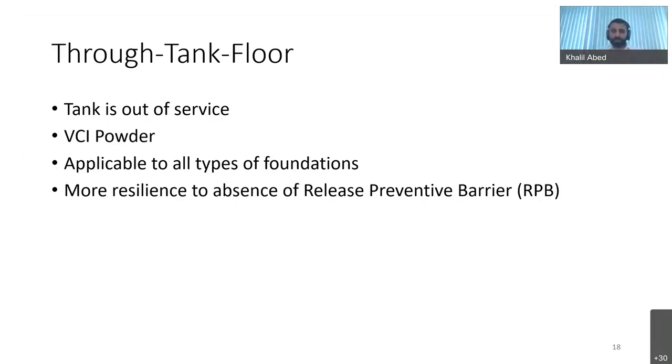So tanks constructed on oily sand, bitumen sand, clean sand, continuous concrete slab. This application methodology is applicable to all types of tank pads, and it's also more resilient to tank foundations that are without release preventive barrier compared to the other application method that I will discuss in the next slides. So that's the through tank floor.